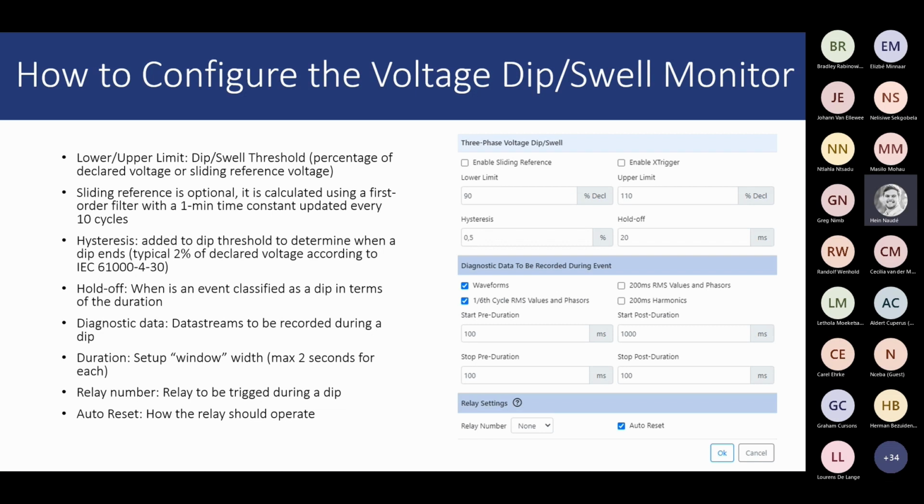And just some background as well: on Osprey Pro, we have a function where you can actually plot the FFT of a waveform. So you'll be able to get an accurate representation of your harmonic spectrum during an event. What is FFT? Fast Fourier transform. It basically characterizes your voltage waveform in a frequency spectrum per individual harmonic, so 50 Hertz, 100 Hertz, 150 Hertz, showing what that component is superimposed on the fundamental voltage and current, if that makes sense.